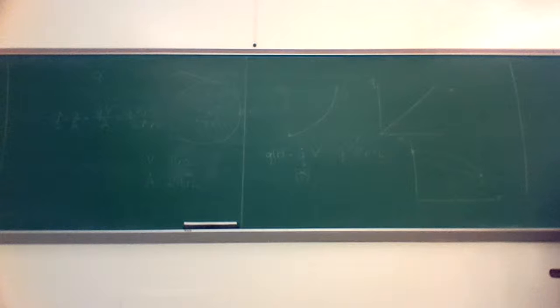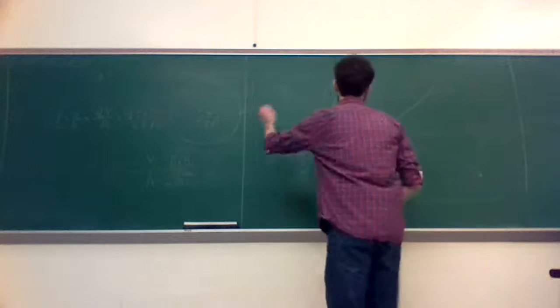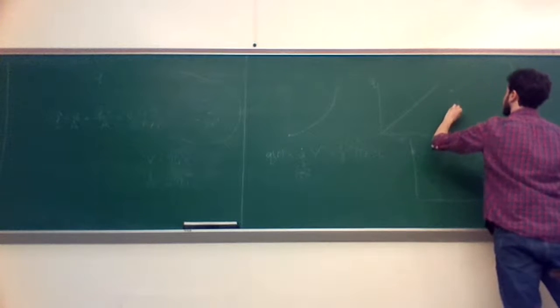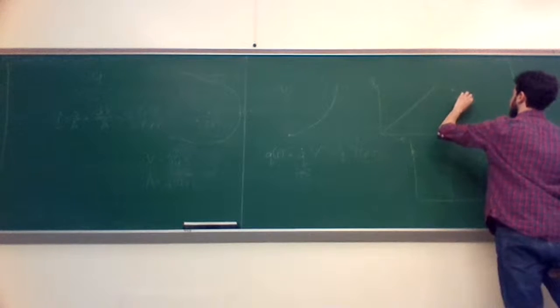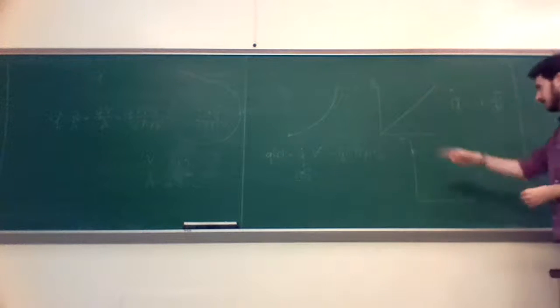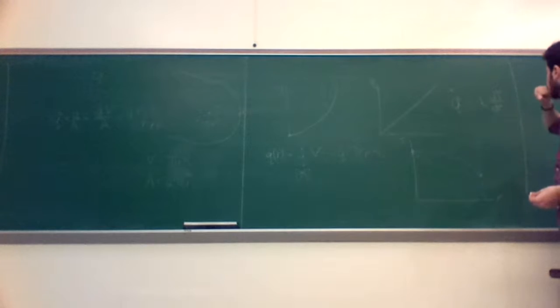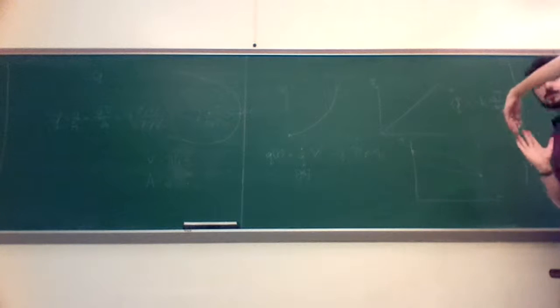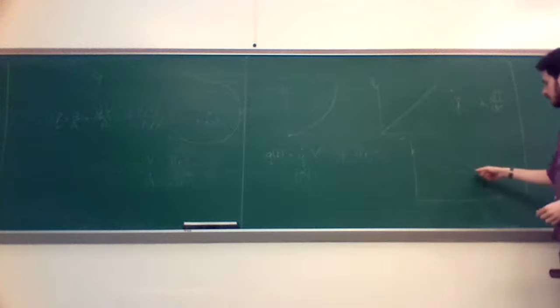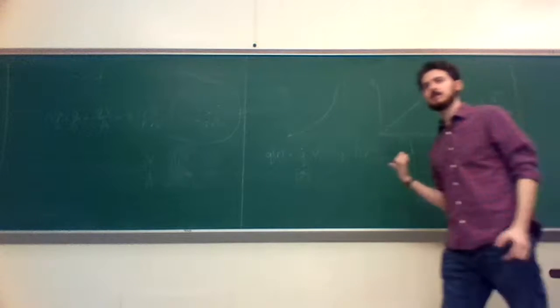So yeah, without going into the big formality of doing a Fourier's law derivation, where you have to do all the substitution, let's use heat flux q equals negative k dT/dr. So we won't include area. We've already got heat flux, so we know it's linear. So if this is big and k is the same, then dT/dr has to be big, right? So this is T versus r, so the slope, negative, positive, whatever, it's got to be steeper. So it would make sense that on the outside, where you've got a higher heat rate, you've got a steeper temperature curve. I think that's the answer. That's all you really need. You didn't need to do some crazy derivation there.